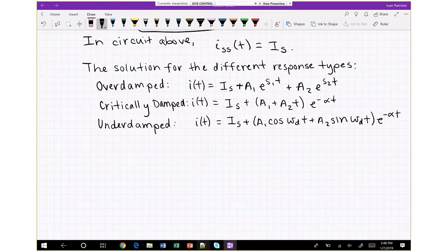We don't use this step-by-step method to find resistor voltage or current directly. We do it indirectly by first finding capacitor voltage and or inductor current, and then doing some circuit analysis. That circuit analysis we do is after the transition.